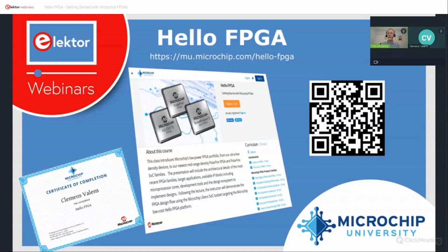There are steps that you might have to do if you're designing an ASIC, like clock tree planning, that you don't have to worry about with an FPGA. So while it might be a little bit more complicated than a CPLD, it's really not that hard to master. And like I say, there are people from all the vendors, including Microchip, that can support you as you're implementing your first design.